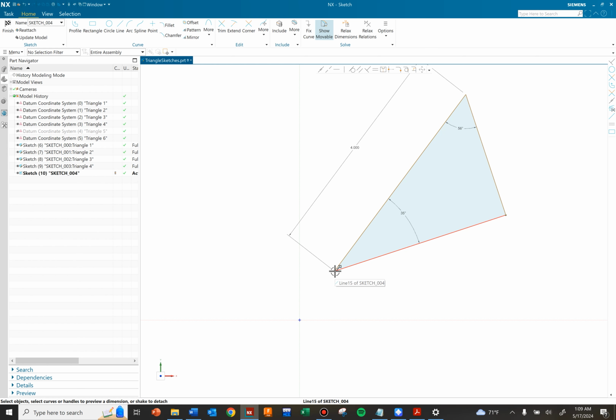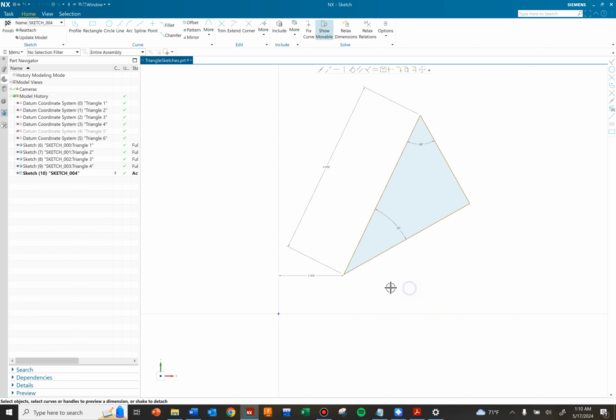So I'll click on the point. We want to make sure that we're actually clicking on that start point. So to make sure that I am clicking on that point, I'm going to wait for the 3 dots to appear, and I can click on the start point, because I want to say from that point to this vertical line. When I click on those two things, I have a linear dimension that pops up, and we're told that this is 1.5 inches. Click off again, and we're going to do the same thing, but to go to our horizontal line. So I want from that start point to this horizontal line. Click on the dimension. This is 2 inches.